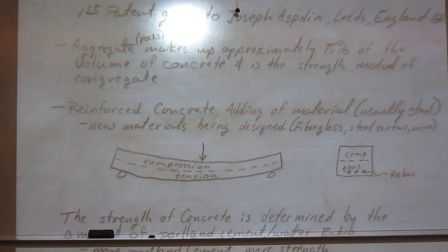But what we'll do on this screen is we'll say that distance right there is 0.75 inches. And so we just crush a whole bunch of rock, run it up a conveyor, and then run it across the screen. Anything that falls through that screen is 3/4 minus. Anything that vibrates off the end of it and doesn't fall through the screen is too big. It goes back around through the crusher.